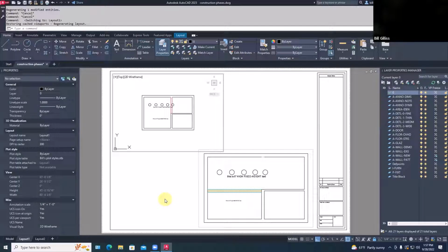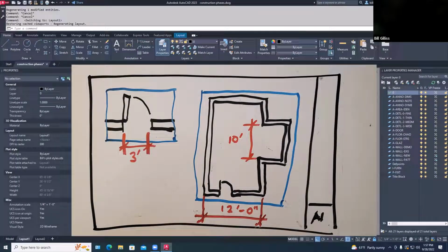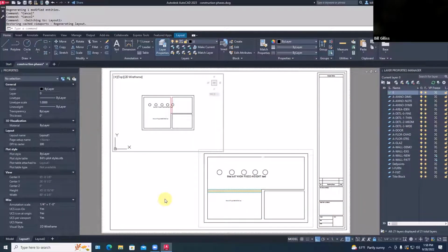The way that Revit works, if we have a title block like this and a view here that's, let's say, a detail at 3/4 inch, and another detail of something else at 1/4 inch, like a plan, you actually do the dimensions on top of the view on the title block. AutoCAD as well is smart enough to realize those 2 points are 3 feet apart. So when you dimension out here in paperspace and click to that endpoint and click to that endpoint, it'll say 3 feet 0 inches. So the dimension can drill down through to pick up the geometry that it's looking at. And that would be at whatever height you decided.